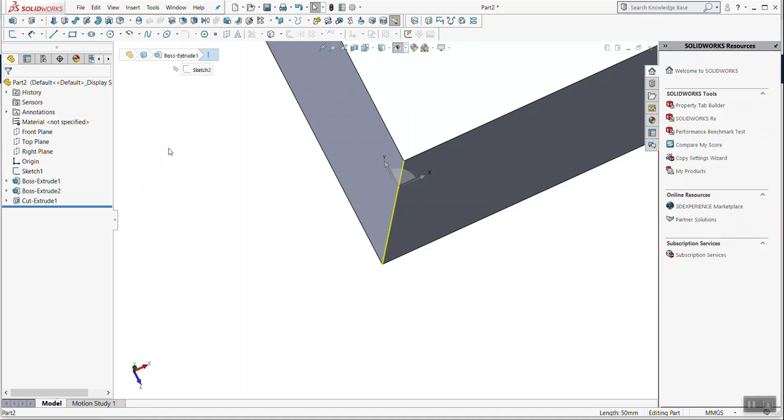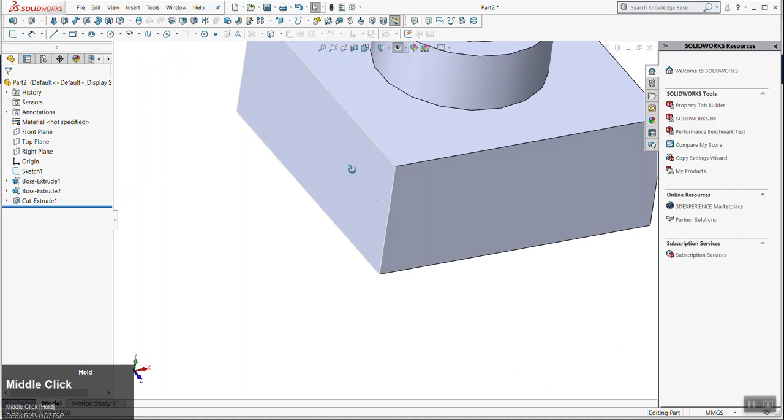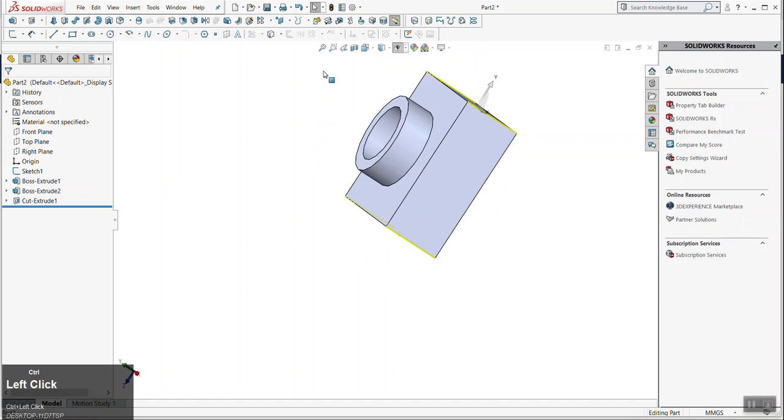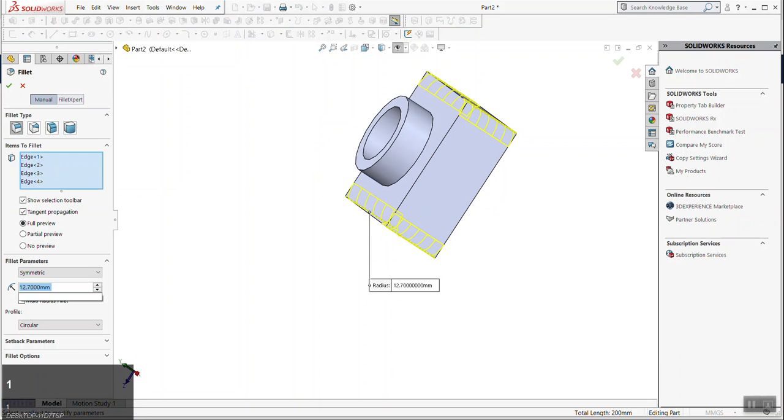The way that I think about it in SolidWorks world and in my head is it is a smooth transition from one to another. So we all know that this is going to be shelled. You guys might be asking me, hey, I thought you said put fillets at the very bottom. Why aren't you shelling it first? Anyone want to attempt to answer that question for me? Why would I put fillets before the shell?